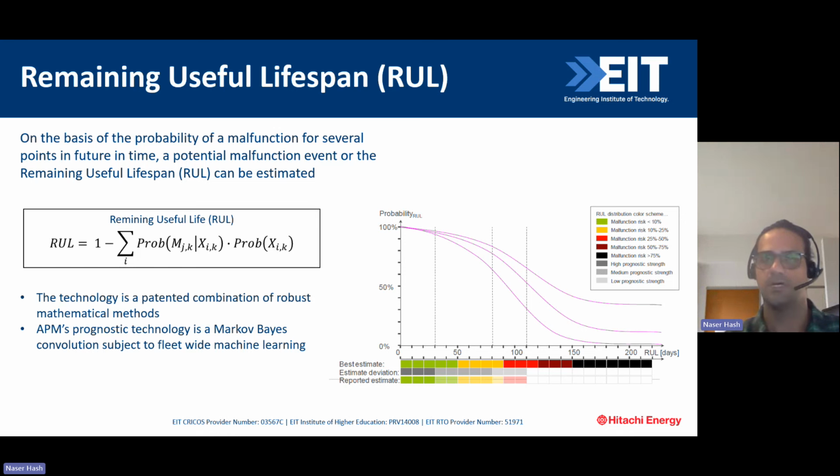That's a huge cost. Also, when insulation degradation has happened, there might be a chance of failure when a transient voltage or a spike in the current occurs, because the insulation has already degraded. So if we have an indication that insulation degradation is going to happen, we can predict that there might be a chance of failure, a short circuit happening for the winding. And we can also predict and calculate the remaining useful life of the equipment as well.